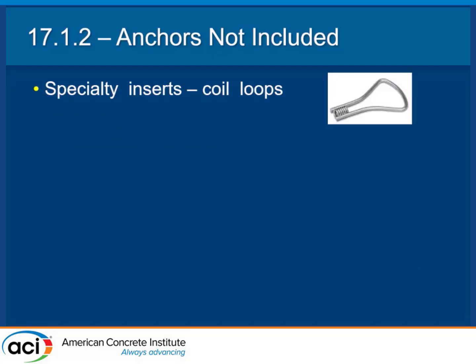So you can start to tell, there are many products, many ways to anchor, and it can be quite daunting, and each one has a little bit of a difference from the other one. So as you get into this, you'll just have to start with one, use another. Necessity is the mother of invention. You're going to design something, you're going to cast in place something, and they're going to say, well, that's in the wrong place, and so they're going to cut the top of the anchor off, and they're going to want to put in a post-installed anchor on you, right? So you're going to get right into it.